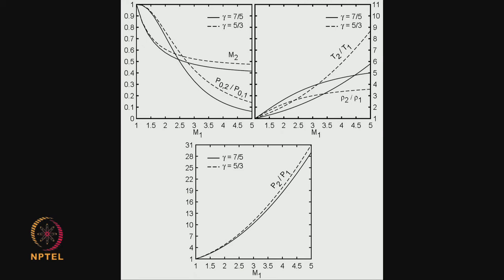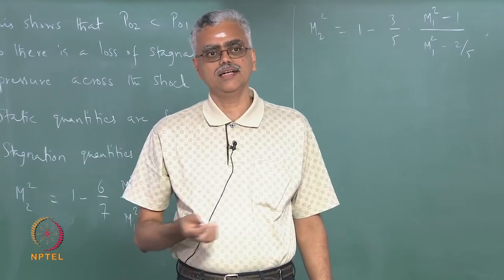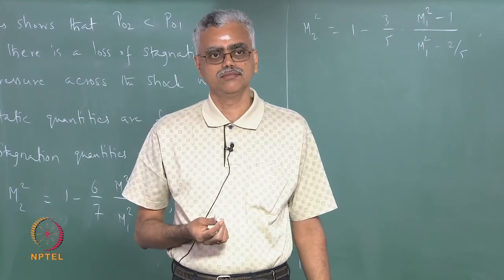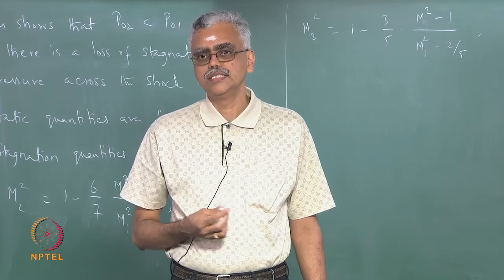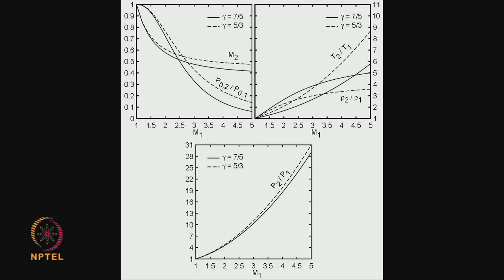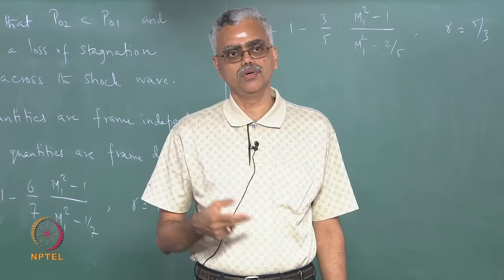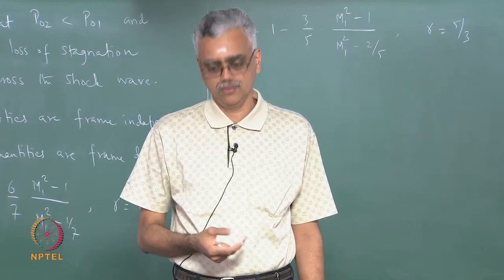So, if you remember our discussion earlier on the aircraft engines, what kind of pressure ratios were we talking about across a compressor? About 30 to 40. So, you can see that when my flight Mach number approaches 5, I can actually achieve those kinds of pressure ratios by decelerating the flow properly. So, my P2 is greater than P1, T2 is greater than T1, U2 is less than U1. That is what has happened here.